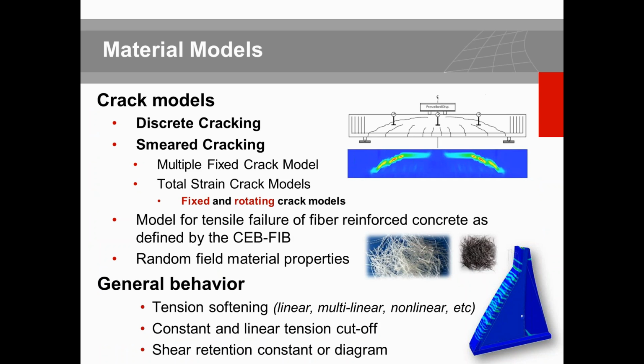So for crack models, we do have different approaches. These crack models could be based on the discrete crack model, which means you can see the crack beforehand on the structure, and you want to see how these cracks are opening, closing, or sliding by variation of the load. In that case, you may come with the concept of interface and dilatancy interface or discrete interface to see